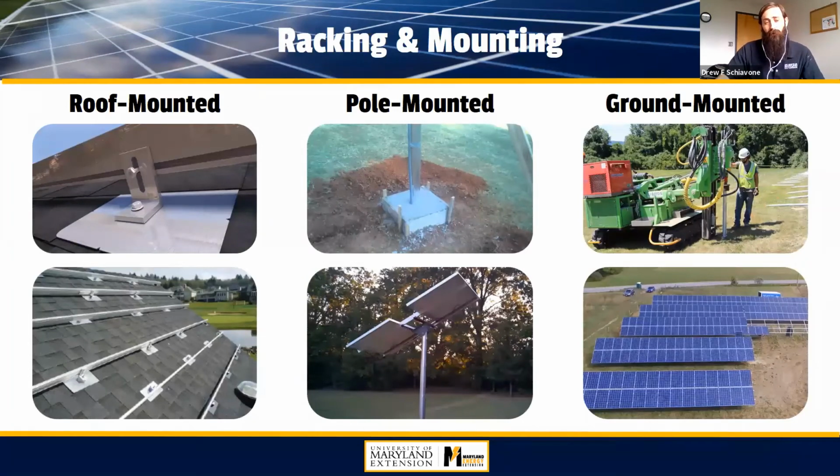As I said, there's a couple of options. The main categories I'll mention are the rooftop system, a roof-mounted system. The example I've shared on this slide is a shingle system, and you have a metal flashing that slides under the shingles. You have an L-foot, an L-shaped bracket, with a lag bolt going through it, penetrating the roof into the trusses within your roof structure.